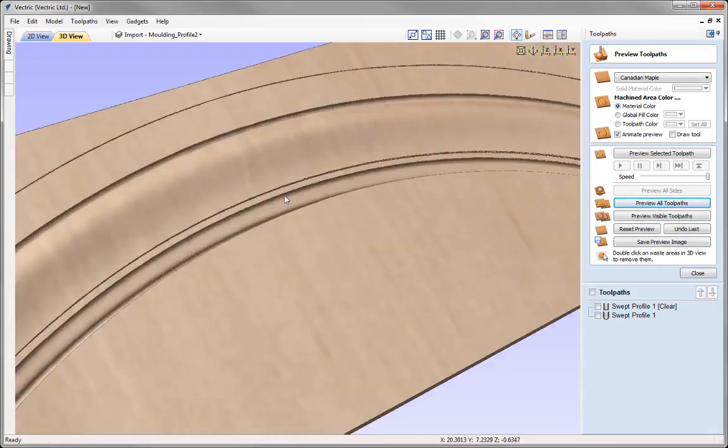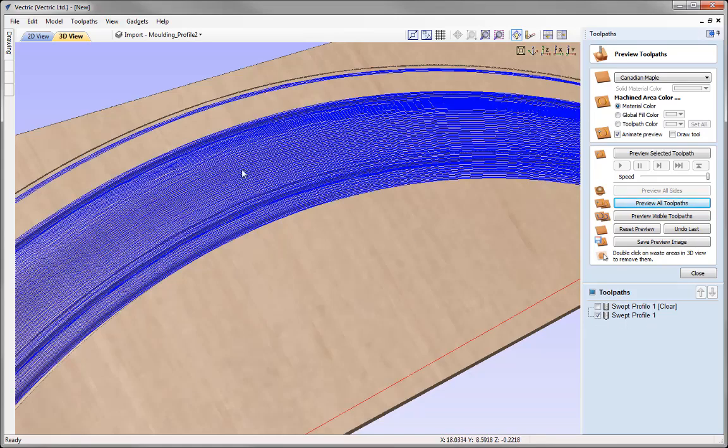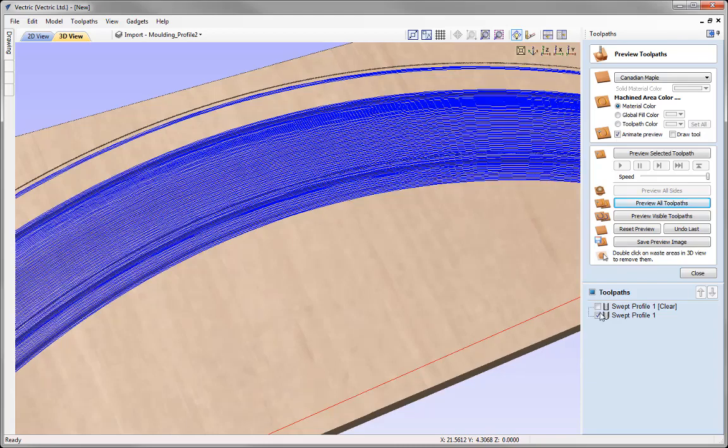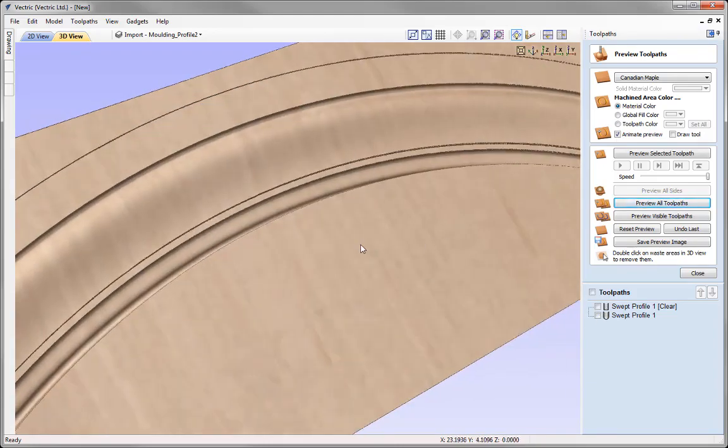We just zoom in there, you can see we've got a real nice smooth finish. If we just switch on the visibility of the finish path, we can see that the toolpath follows the drive curve, and so it's going to create a very clean finish as it's following the curve, and it isn't trying to do a step over which isn't in sync with the shape that we are cutting. Now there is no 3D model here that it needs to be projected down onto, so the quality is going to be very good. So we can see that just by looking at our preview here.